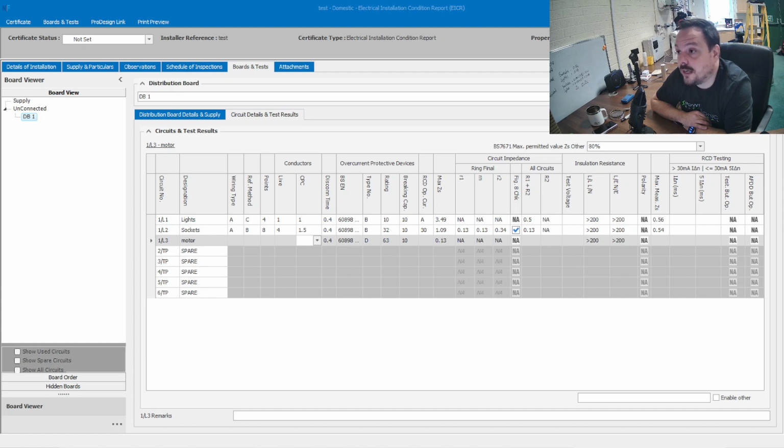So that's the purpose of my little series of videos here, is to show you how calculation will play out and give you figures that are valuable and can help you, on small domestic and small commercial. If you just want to use the calculation method and you've got a team you trust to put the conductors and terminations back properly, perfectly acceptable. It's in Guidance Note 3. You don't have to go and record the live measured value if you don't wish.